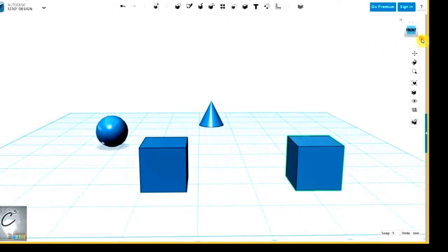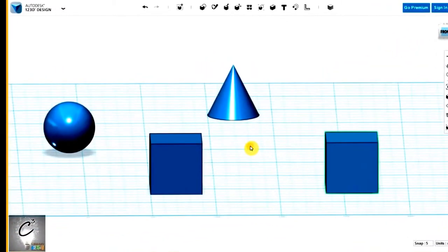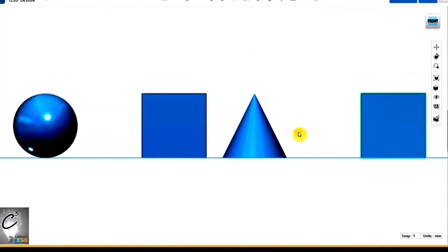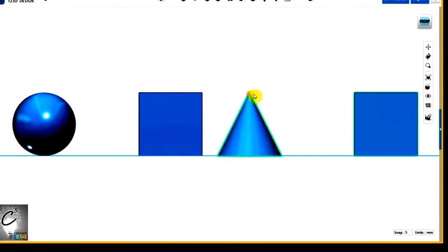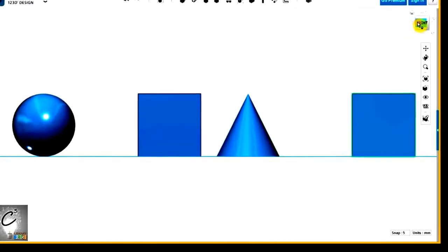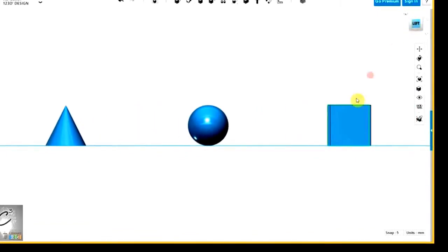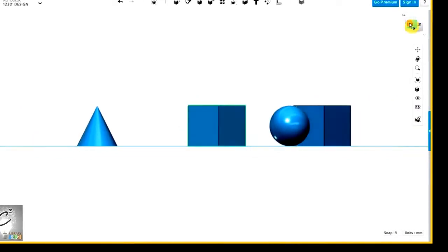But sometimes when you're designing, you want to be able to get a real sense of what the actual measurements of these things are relative to each other, without regard to how far away they are. So down here in the little drop-down menu under the view cube, you can set it to orthographic. Right now we're in perspective, and if I set it to orthographic, it's going to look a little bit less natural when we're just looking at it from an angle, but if we switch it to the front view, you can see all of these objects were actually the same height all along, but you weren't too sure about it when looking at it from the perspective view. If you pan around, you can look at it from a different arrangement. Of course, you won't see the cube behind there very well, but you can see that they're actually all the same height.